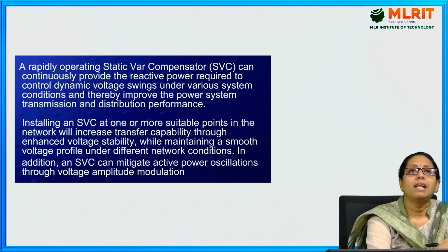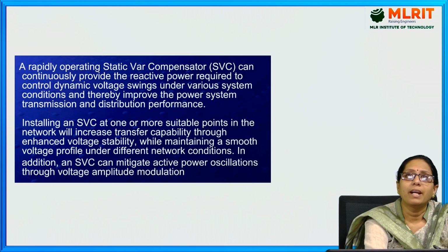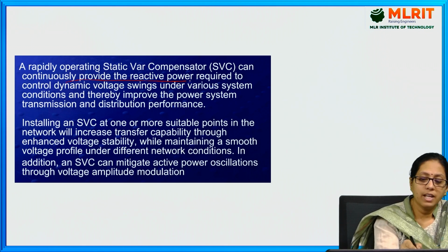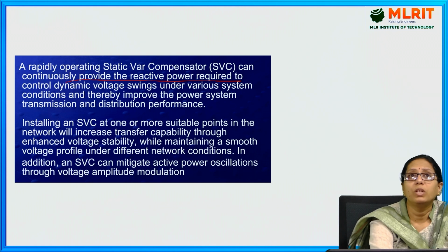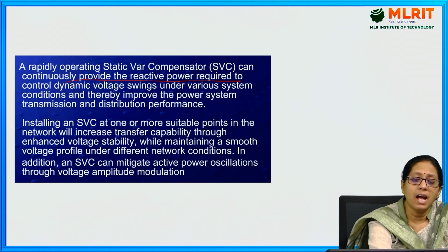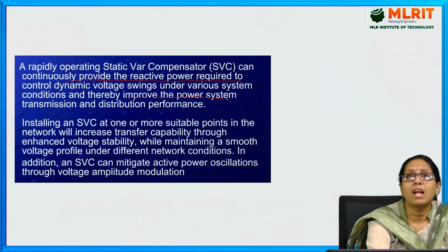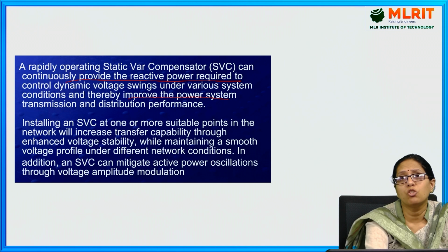A rapidly operating static var compensator can continuously provide the reactive power required to control dynamic voltage swings under various system conditions, and thereby improve the power factor, as well as the transmission and distribution performance.